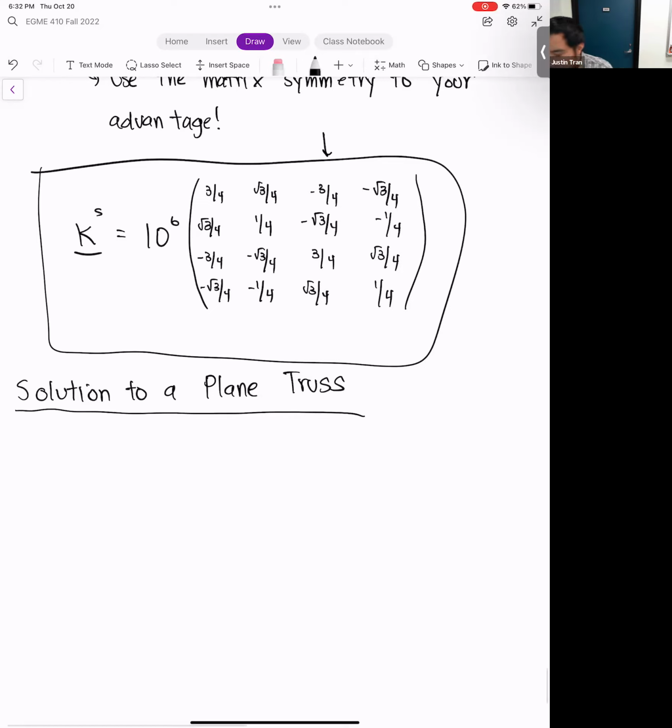And before I start this example, whenever you're doing a full finite element problem, it's useful to remind ourselves what the 5-step process is. The first step is to discretize the geometry and to label the elements and nodes. So remember, it's discretize, that's label. Second step, once you've labeled all the elements and nodes, is to compute the element stiffness matrices for all the elements.